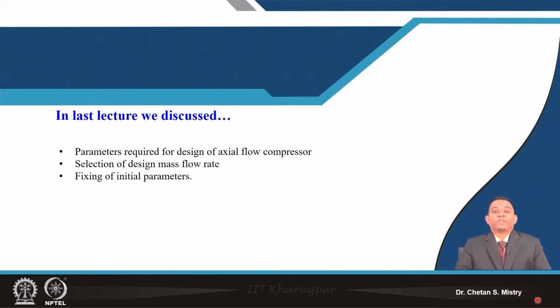We realized that for the initial stages, the pressure ratio is large and the efficiency we assume to be lower, because the flow will be going transonic in that region. For middle stages our expected pressure ratio is moderate, but our efficiency is on the higher side, because of the flow uniformity we achieve in the compressor.